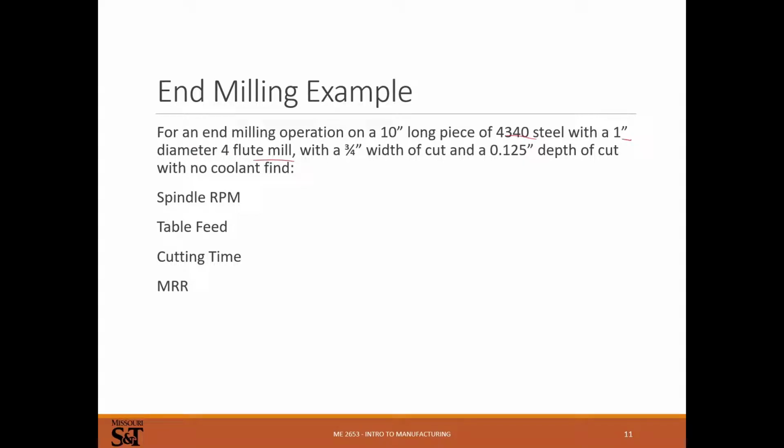You usually use 4-flute on steel. We're only going to do a 3/4 inch width of cut. We're not going to do the full 1 inch. We're going to do a 1/8 depth of cut. So we're only using 1/8 of an inch of our cutter.